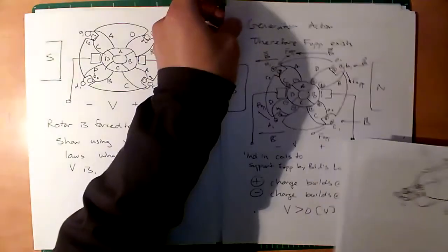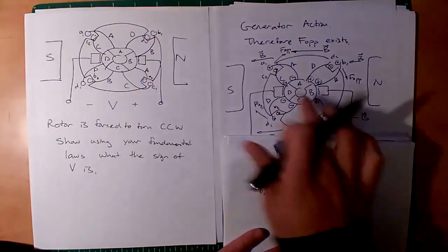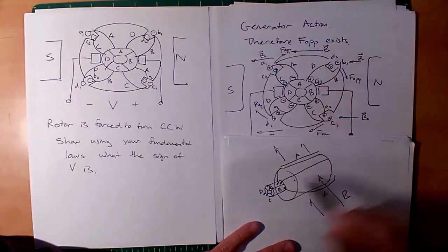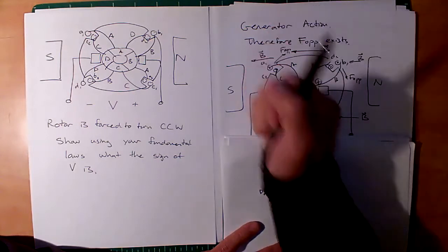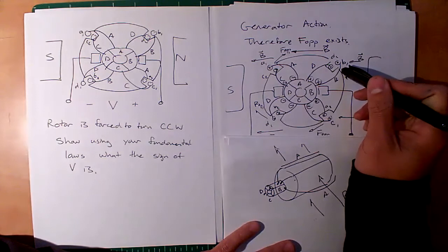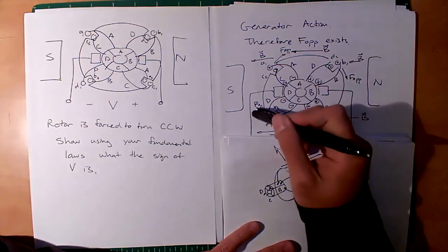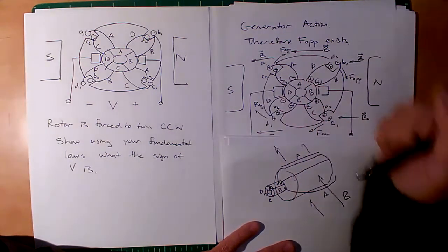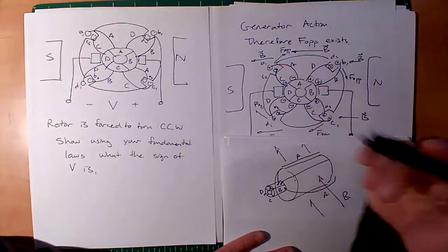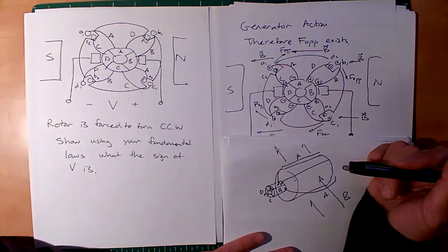So I have this next figure here, and this is just the same thing redrawn, but let's see what's going on. In all these coils here, you can imagine if I'm rotating it, some external prime mover is rotating counterclockwise, there's going to be a force always in the opposite direction of rotation, always opposing. And the reason why it's opposing is due to Faraday's law, Lenz's law, the physical nature of the device.